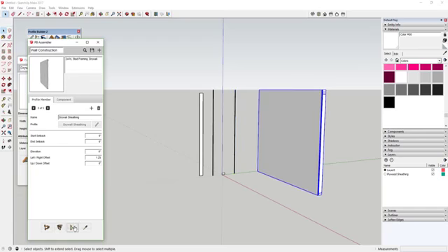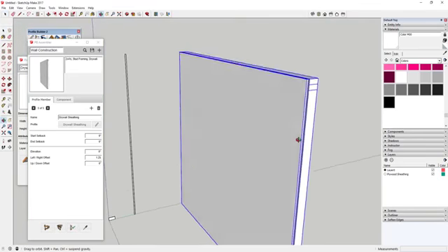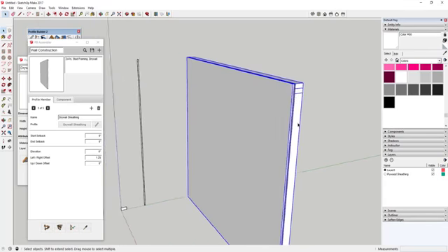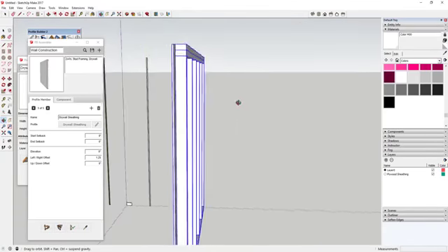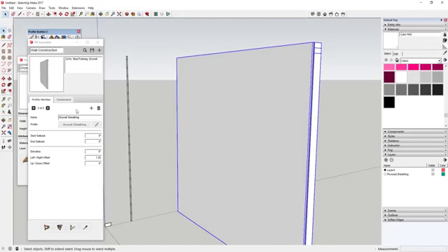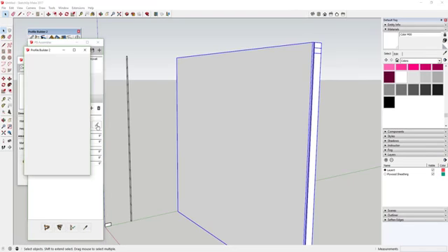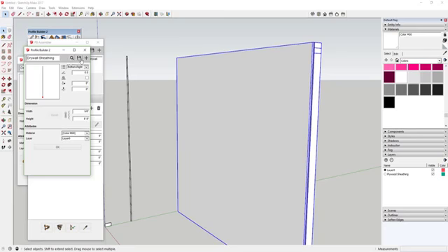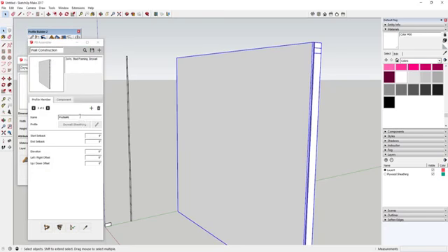So now you can click on this object and click update. And now you've got a layer in here of chipboard, and you've also got a layer in here of plywood on one side of your wall. So you're just going to come in here and add one more. You're going to do the same thing. You're going to select that drywall sheathing and hit OK.